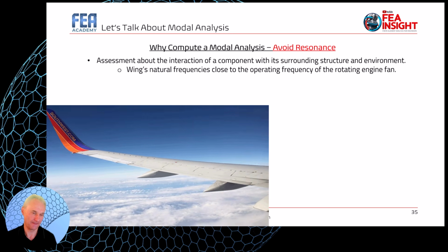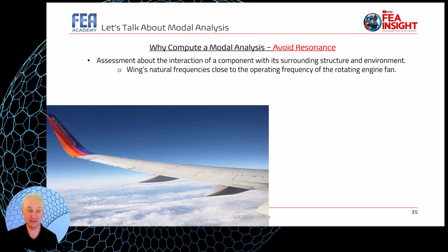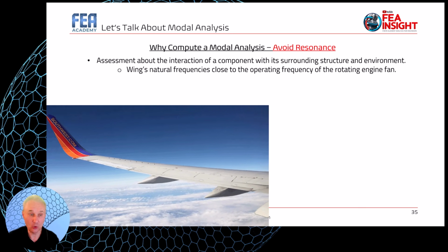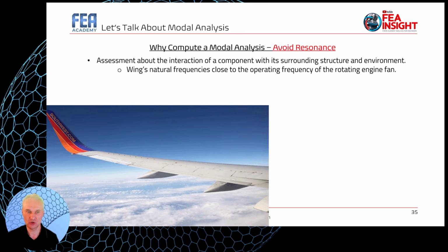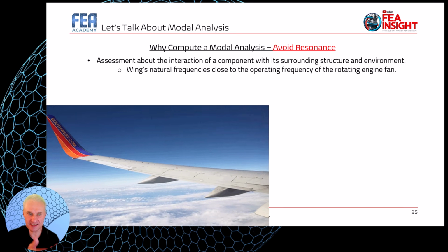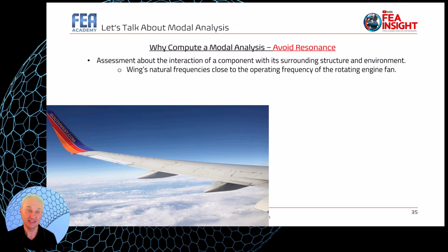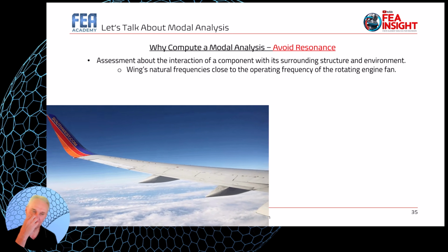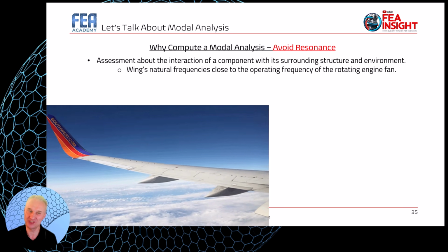the engine. If this excitation frequency is synchronized with the natural frequency of the wing, the wing will be destroyed by this excitation. So the operating frequency of the rotating engine fan needs to be completely dephased compared to the natural frequency of the wing in order to avoid the destruction of the wing.